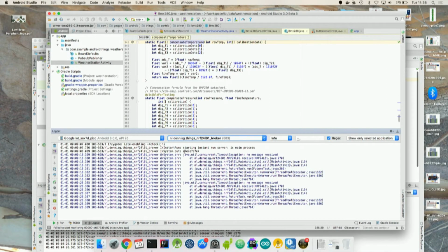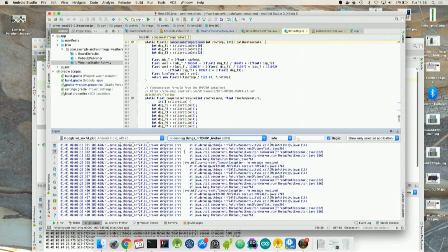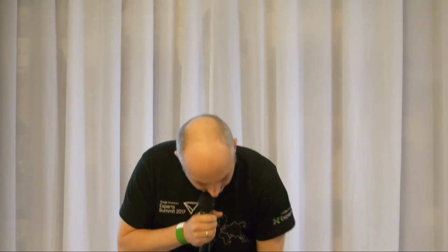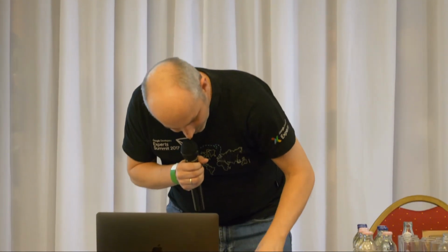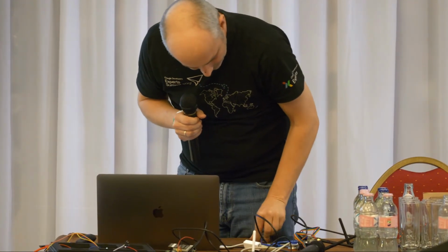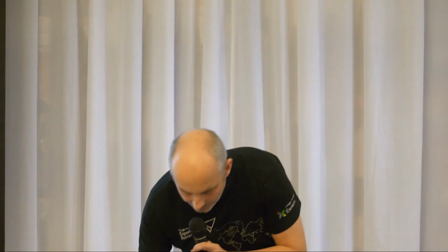Okay. So I have this other board. It has two antennas. One is the Wi-Fi antenna, and the other one is the NRF chip, a radio that is able to listen and send data at 2.4 gigahertz. I've set the channel and everything, and now if all is well, if I turn on this Arduino, there should be some output. Let's restart this one.